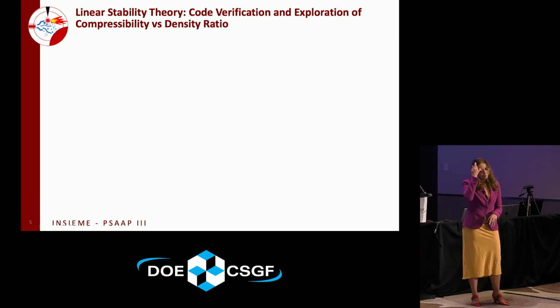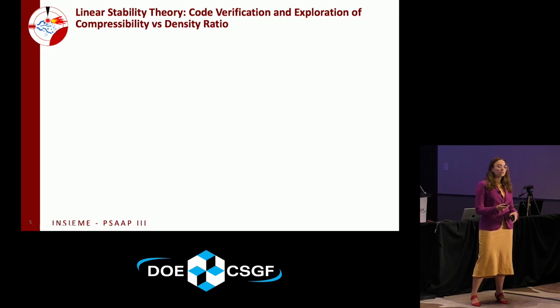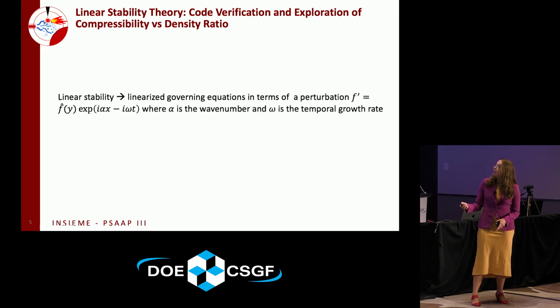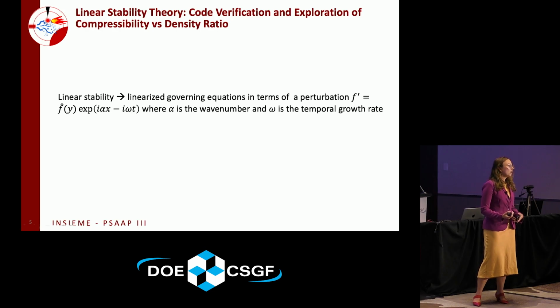Now I'm going to talk a little bit about linear stability theory. So again, what I'm interested in is a two-phase shear layer where we have the liquid stream and the gas stream. And one way we can verify our method as well as explore the physics is to look at linear stability theory. What it is, I linearize the governing equations in terms of a perturbation where we get the temporal growth rate of the shear layer for different wave numbers. So with this, we're able to see if the method accurately captures the early stage evolution of the shear layer, so its physical properties, as well as we're able to investigate different effects of density and compressibility on our shear layer.